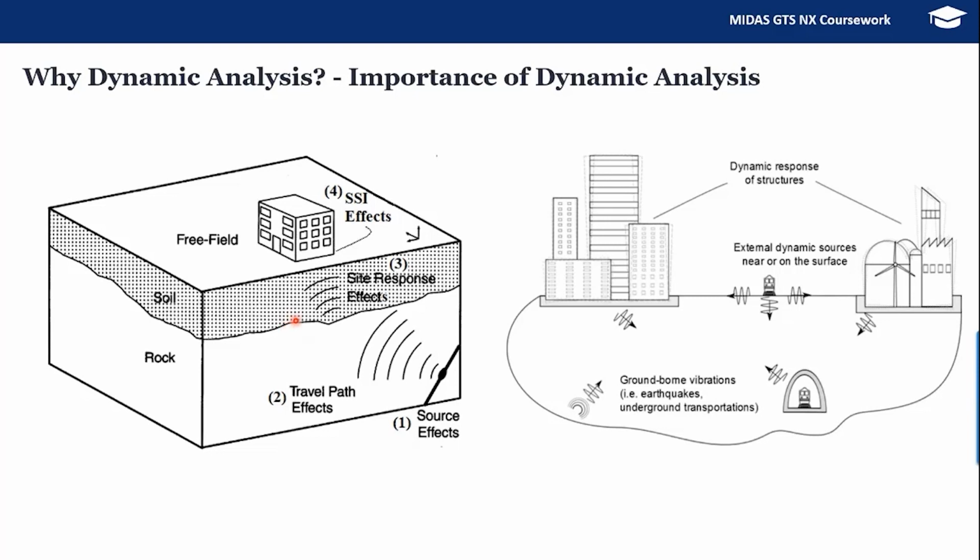And then we run the different loading conditions, like the earthquake load, the wind load, and all the static loads. We do proper codal combinations of loads, and then we go for design. That's as simple as that. But for earthquake loads, we do run response spectrum analysis, and in some cases we go for time history analysis. But the important thing is we need to consider the effects of the soil continuum as well.